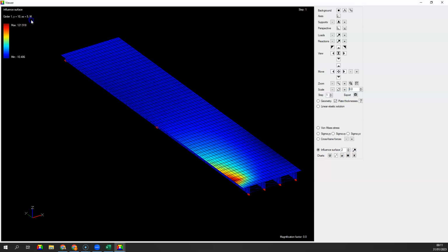Okay, so the moment here, this is the influence surface for the moment on girder 1 at y equals 10 feet from the abutment for cross section node number 5. Here, we don't need this number because again, this is an integration of the stresses over the composite section. We can look at the truck configuration leading to this maximum moment, which is here equal to 9,600 kip inches.